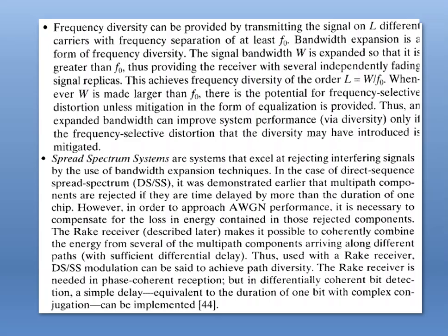The rake receiver needs phase coherent reception, but differentially coherent detection with a simple delay equivalent to the duration of one bit, with complex conjugate, can be implemented.